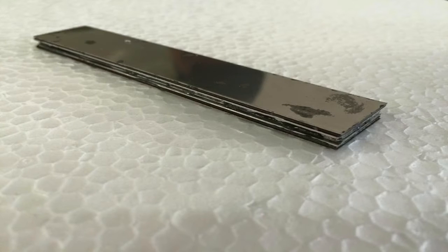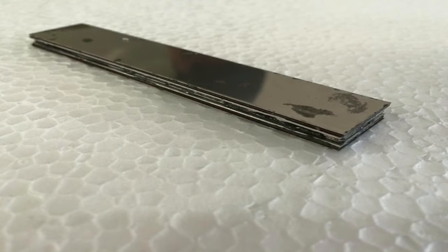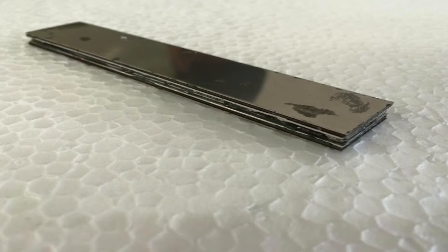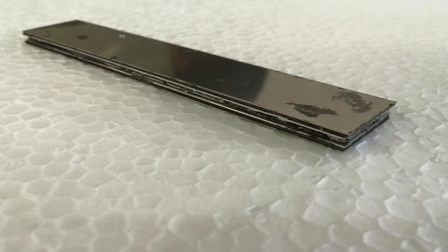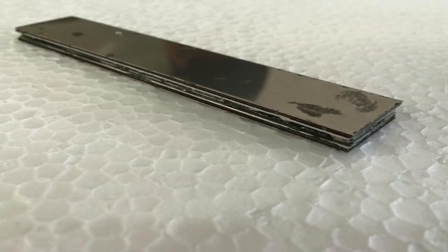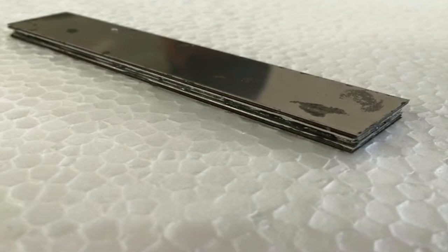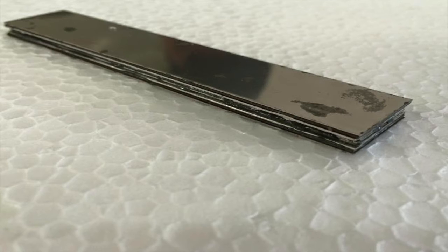Third, from calculation, we can notice that the layers closer to the neutral axis give more allowable moment, and some layers can handle the maximum moment of the 950 Newton load. So, we set those layers to the lighter weight material, which is aluminum.